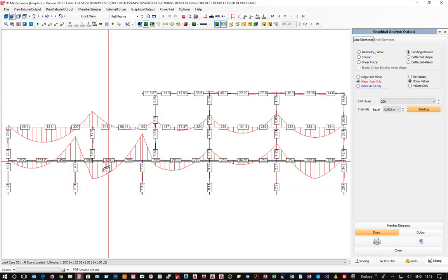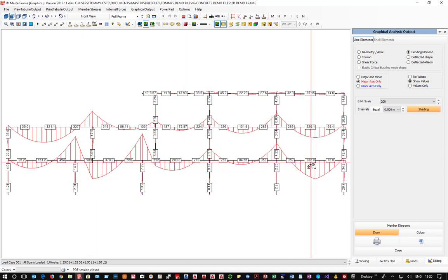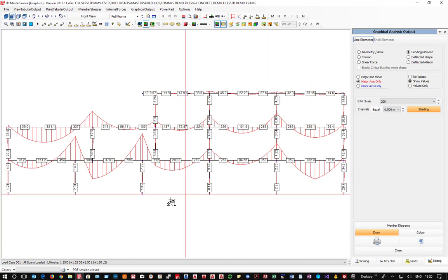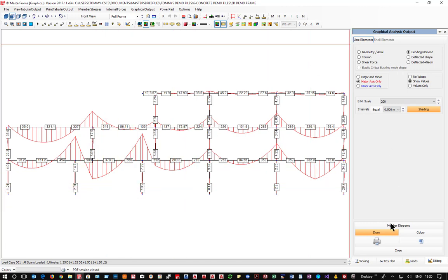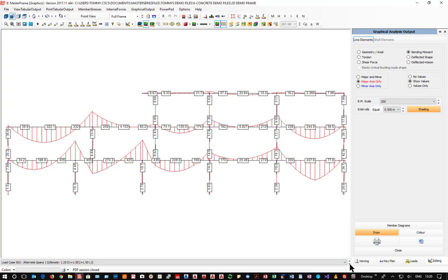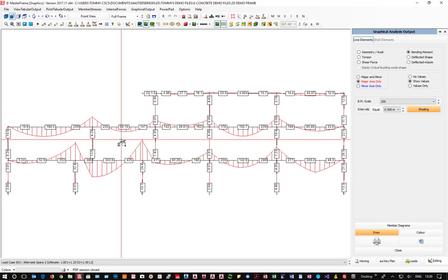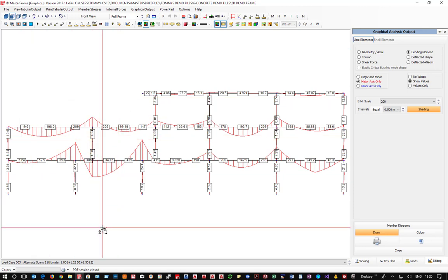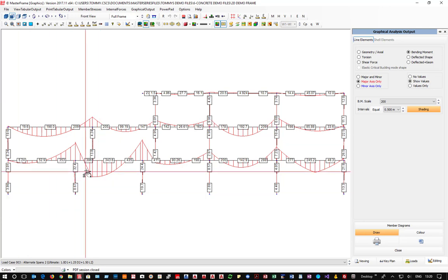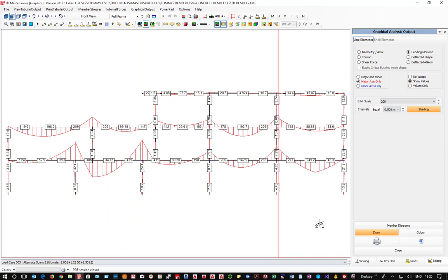So that value of 338 is the moment due to the dead and live load maximum on all spans, and likewise that's 382. So remember those two values. If I then look at a different loading case, you'll see that that goes down and then it comes back up again. It comes up to a slightly higher value because of the alternate loading, and in this case actually the column is probably causing it not to go down as far.